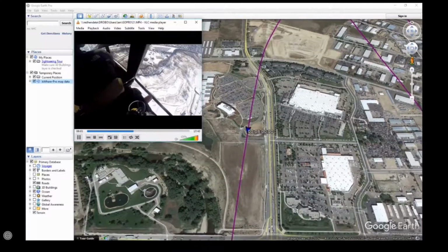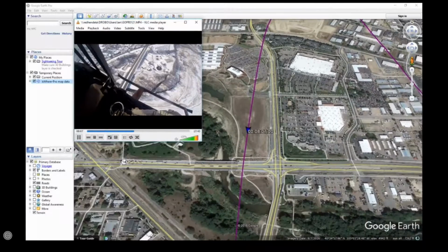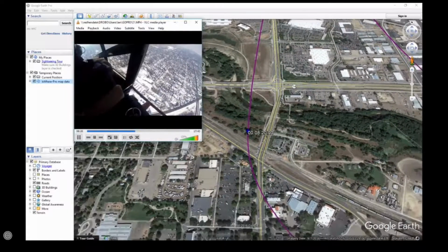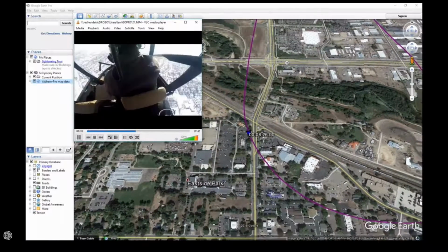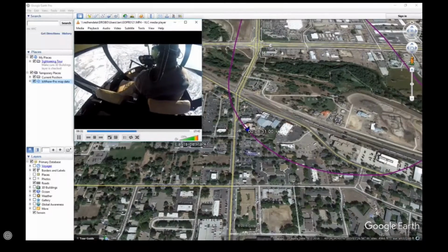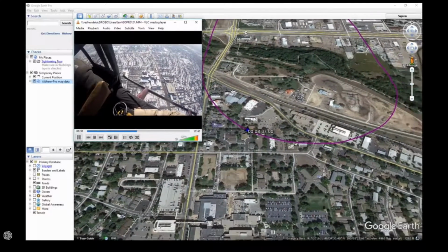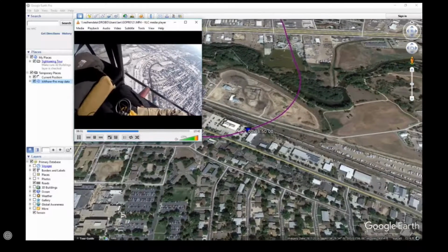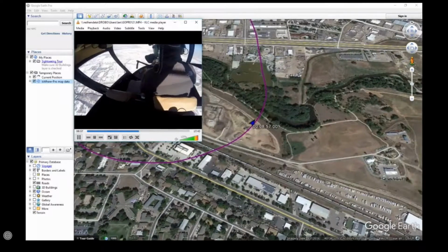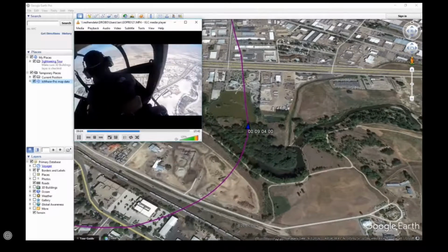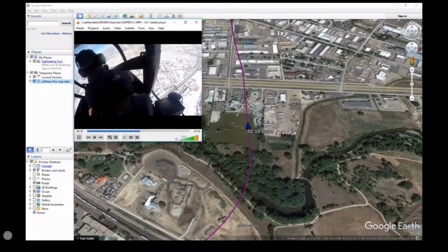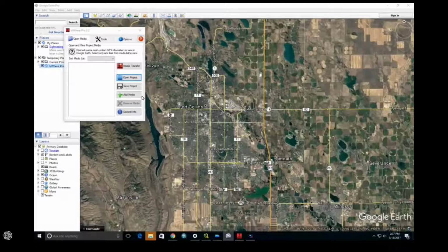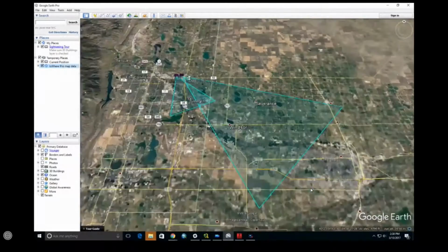And there we go. The other information that we're getting out of the DMRT is distance to target. So that's a fairly approximate value, plus or minus 5 meters of range on a non-reflective target, whereas on a reflective target, I think the Vectronix laser that we're using in this kit has maybe plus or minus 2 meters of accuracy. So this was actually put together post-process using a 4Trax 401. Yeah, it was a 4Trax GPS logger and then just a GoPro mounted on the user's head. And in post-process, we were able to geo-reference the video using a track log. So if we have multiple videos, we can also do a batch process.